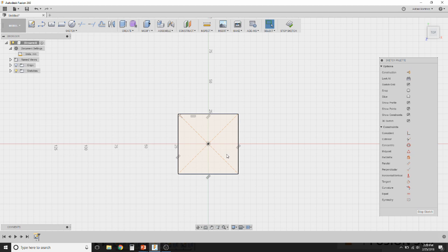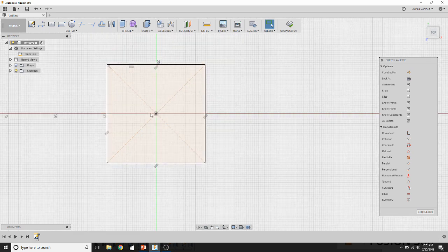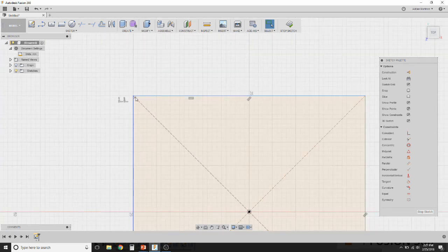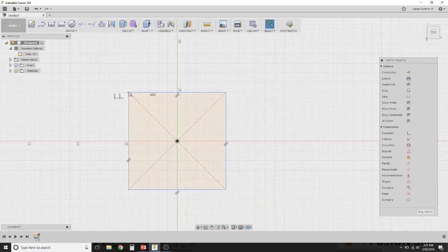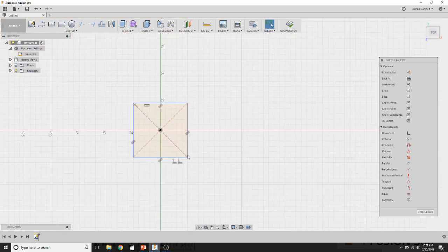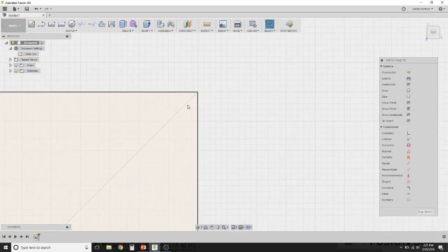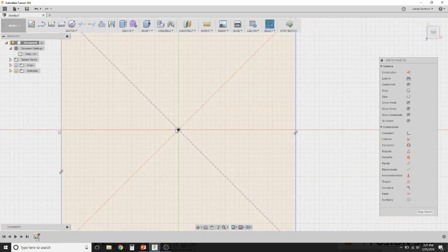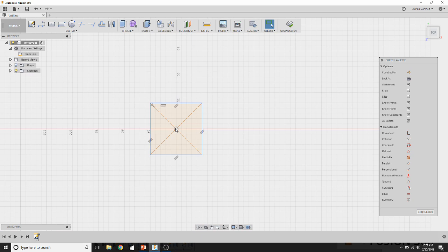Okay, to navigate around your drawing space, if you use the wheel on your mouse, you can roll the wheel one direction to zoom in and roll the wheel the other direction to zoom out. That's one of the ways I get around my drawings. Now, if you put your cursor over a specific area and zoom in, it'll actually go exactly where your cursor is going. So go ahead and practice that. Zoom into the corners of your cube and then zoom back out. Anywhere you put the cursor, it's going to let you zoom in and out of that specific area.